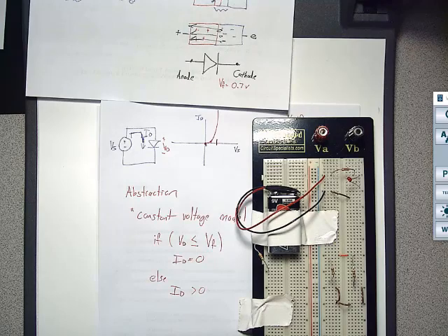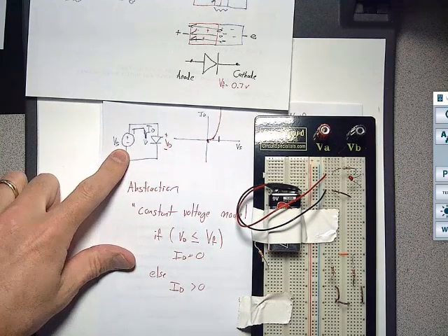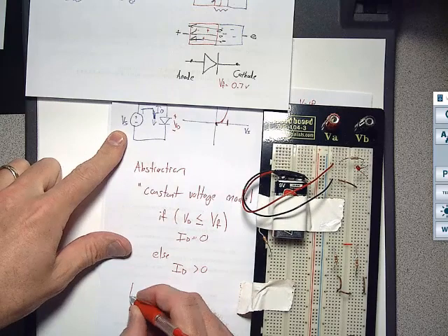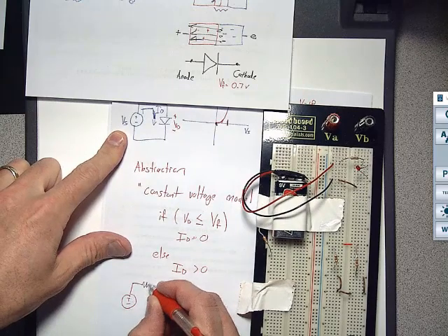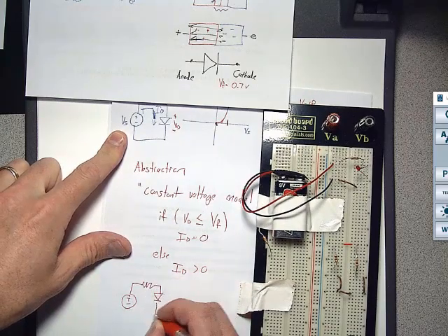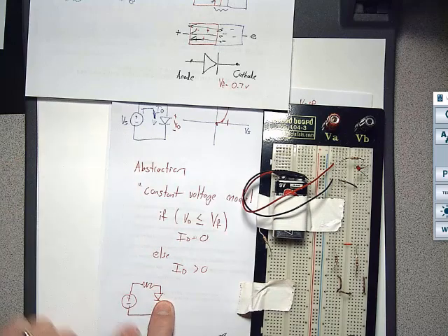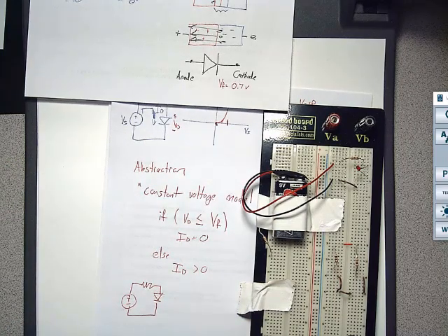So all you got to do is say, here's a diode. I'm going to find out what its forward voltage spec is. And what I need is to increase the voltage at least up to that to get it to turn on. And then if I go above that, the voltage across the diode will never change. In this circuit, this is no good. But if I did have a circuit like this, which is usually what you have, like a resistor and then a diode, the voltage that doesn't develop across the diode will develop across the resistor.